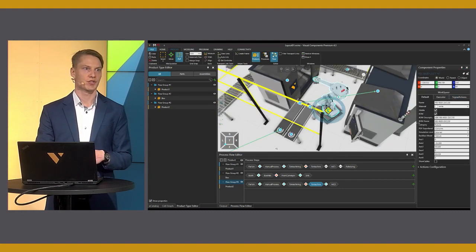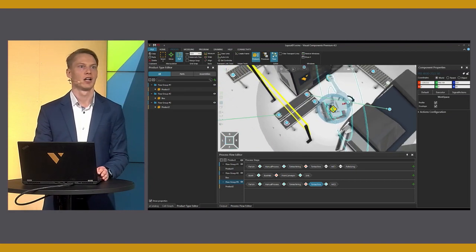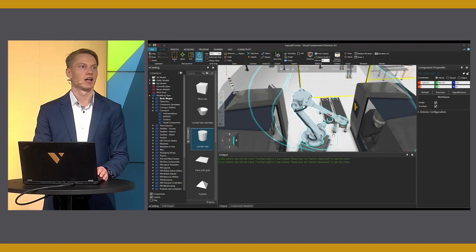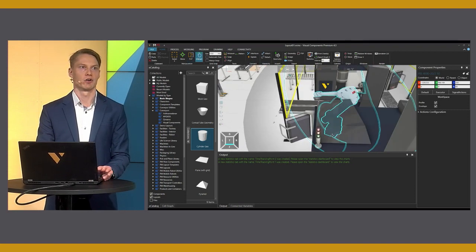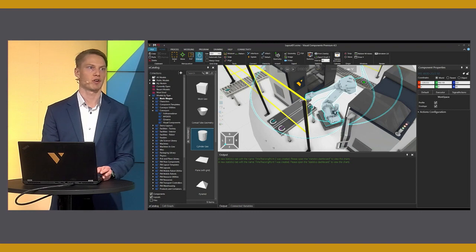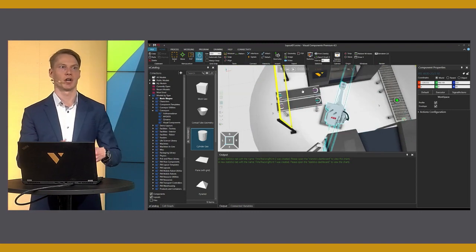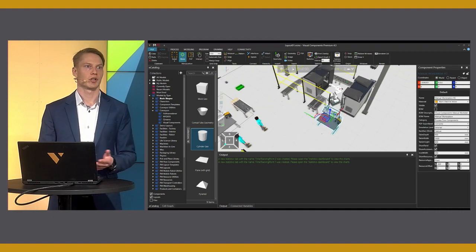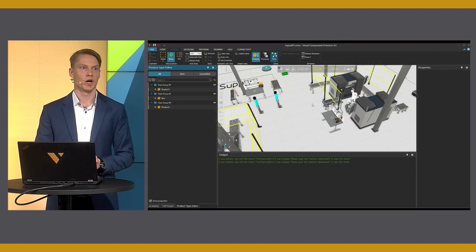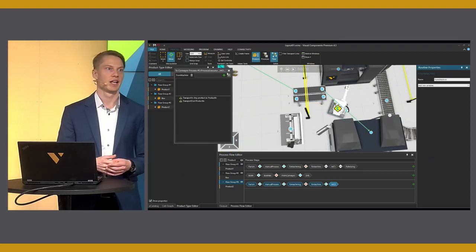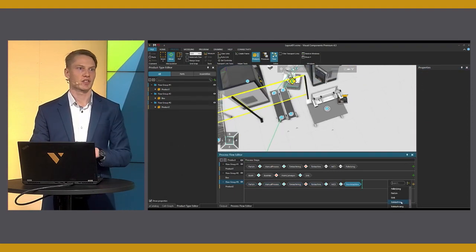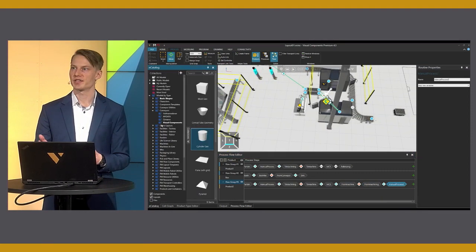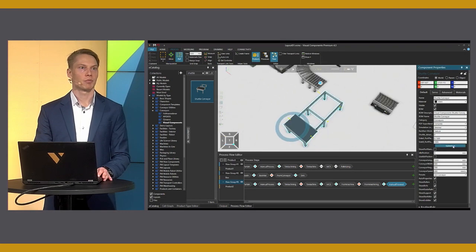Then renaming the process as studying the reach for the robot to drop point on the conveyor. That can be done with visual aids or by trial and error when the robot program and the simulation has stopped due to unreachable position. Detecting those scenarios is crucial, without a doubt, and one of the reasons to simulate in the first place. So in this case, we just placed the robot with the visual aid. Then adding the new process there, the manual process.